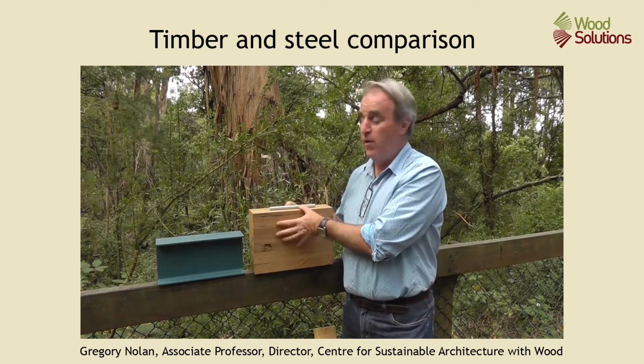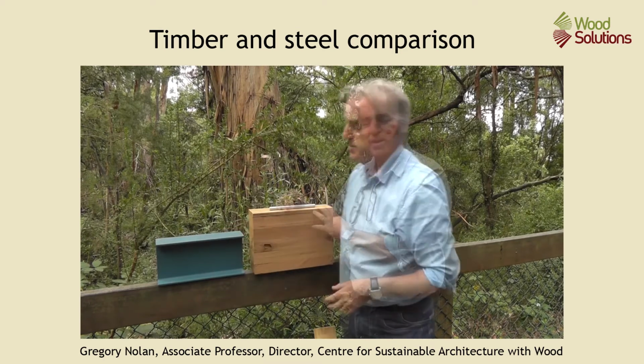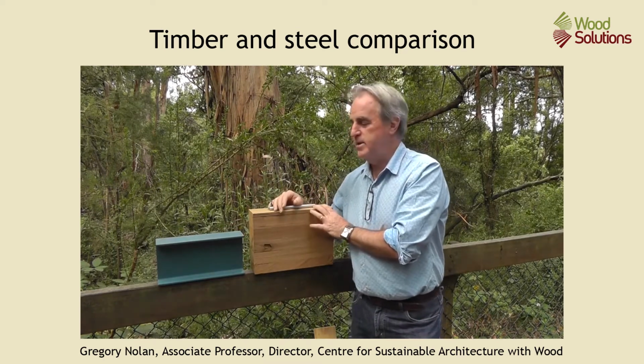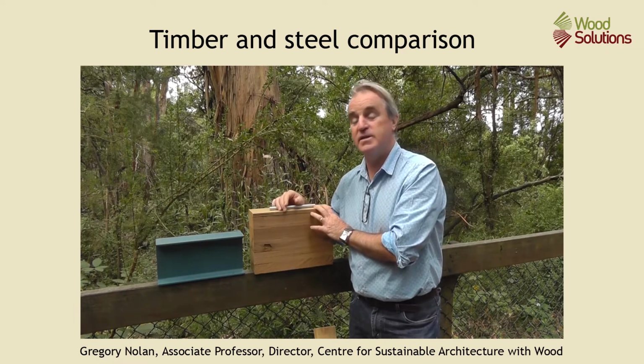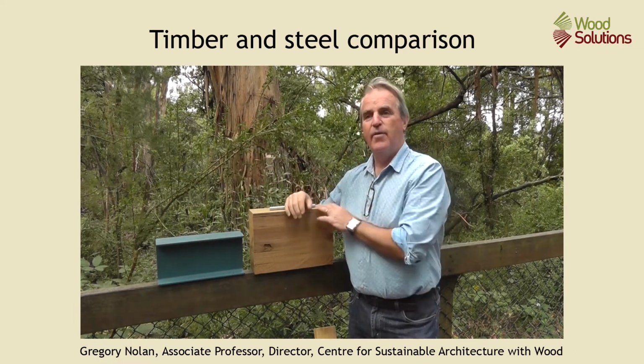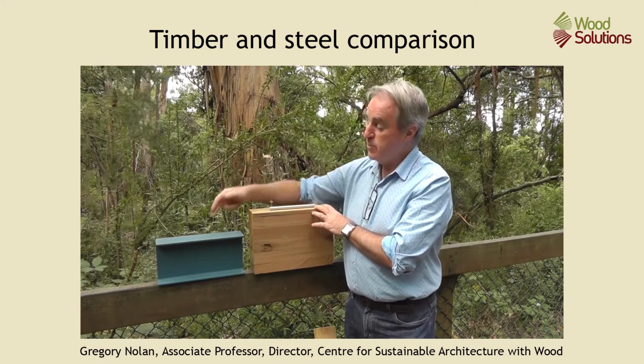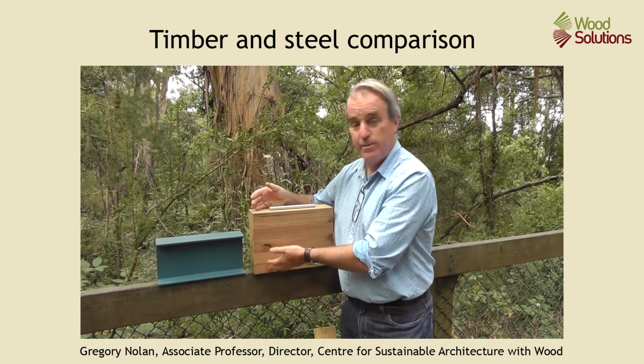This is about 4.5 kilos, this is about 4.4, 4.3 kilos. So these pieces have been selected to have exactly the same bending stiffness. That means if we used either of these in a floor, then they'd be interchangeable. So they're the same weight. This one isn't as high as this one, so this one's a bit bigger.